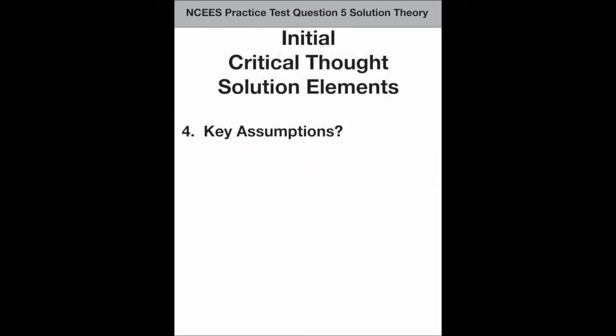4. Are there key assumptions? Yes. First, assume sea level conditions for psychrometric analysis, as no other altitude is given. You must always identify altitude when considering air conditioning processes. Second, assume steady flow conditions for energy transfer. This assumption is nearly universal for PE problems. Third, you must assume that the water being removed is standard in its density, specific weight, etc.